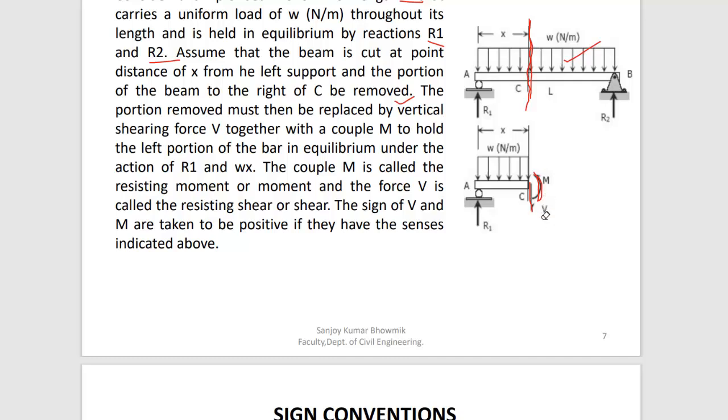Here you can see that we don't yet know the R. So we need to calculate V and M. From this structure, if you take the summation of vertical forces, you have 2 unknowns, R1 and R2. Are you getting the concept? You need to go back to a little bit of basic mechanics. How do you calculate the reactions?